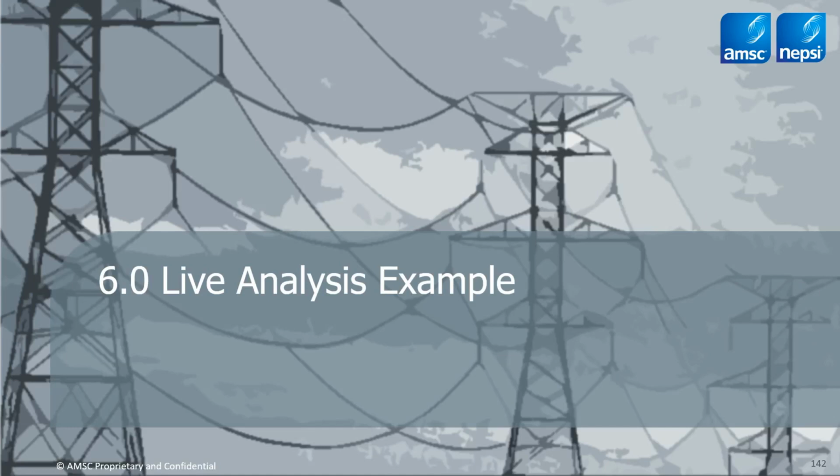Do multiple subcycle switching of tuned harmonic capacitor banks cause a harmonic concern? Subcycle switching, okay, so that's a transient condition. If you're concerned about the switching of a filter or a capacitor bank and whether it's going to cause a concern, you need to perform a transient analysis to see how the voltage on the waveform might peak, or how fast it'll ring and how long that will last. That's not a harmonic concern.